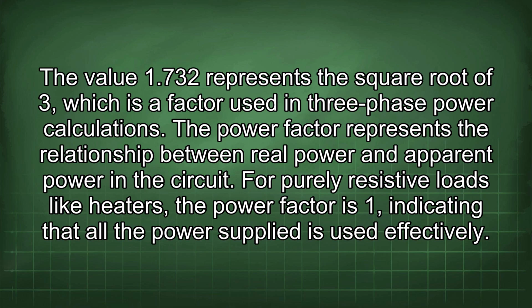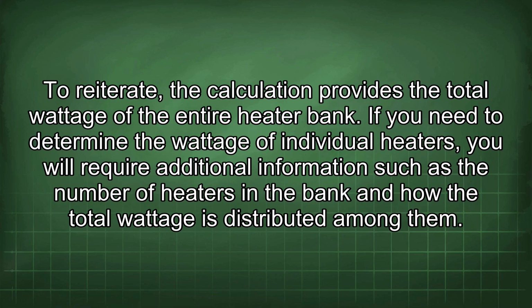The power factor represents the relationship between real power and apparent power in the circuit. For purely resistive loads like heaters, the power factor is 1, indicating that all the power supplied is used effectively. To reiterate, the calculation provides the total wattage of the entire heater bank. If you need to determine the wattage of individual heaters, you will require additional information such as the number of heaters in the bank and how the total wattage is distributed among them.